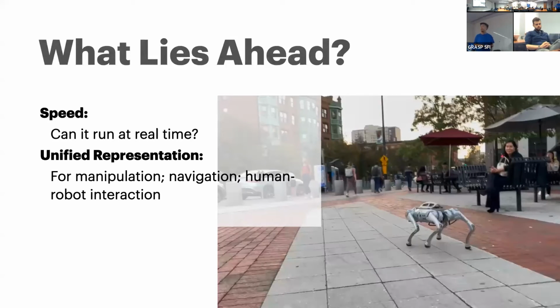And the direction is to make NeRFs generalizable, and in fact make generalizable feature fields. It also means you probably want to change the kind of sensor you use. For example, with a single camera, you don't really get scale invariance. Maybe do a dual camera setup, so they have a fixed baseline. Maybe instead of two regular perspective cameras, you do two Insta360 cameras. You're going to get more out of it.